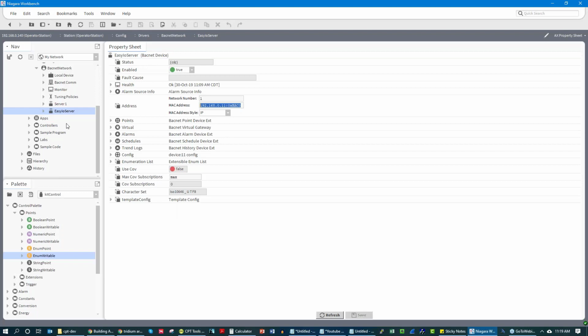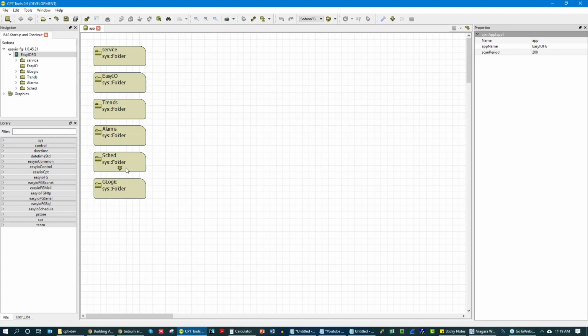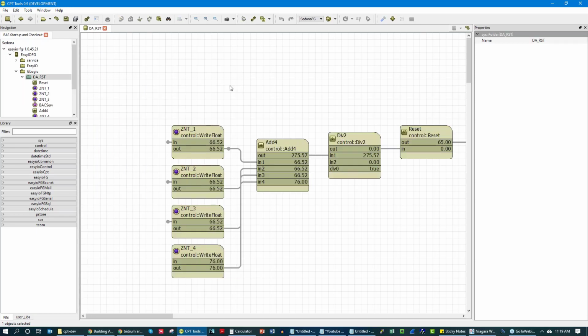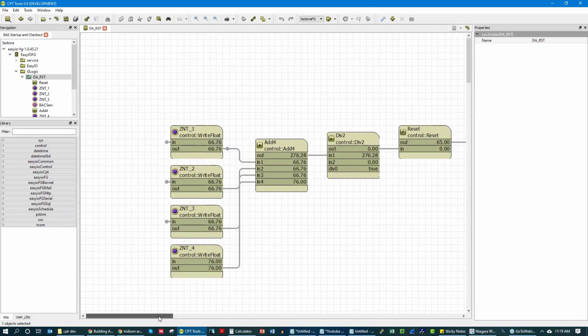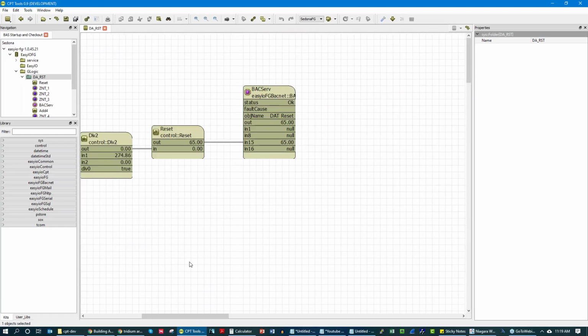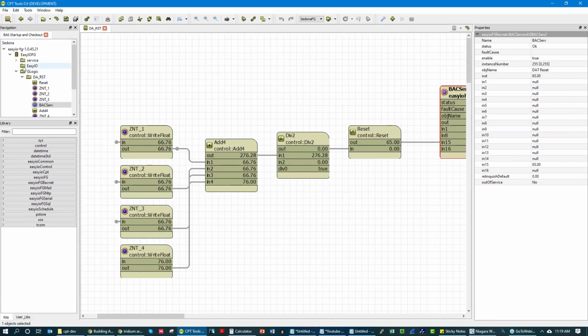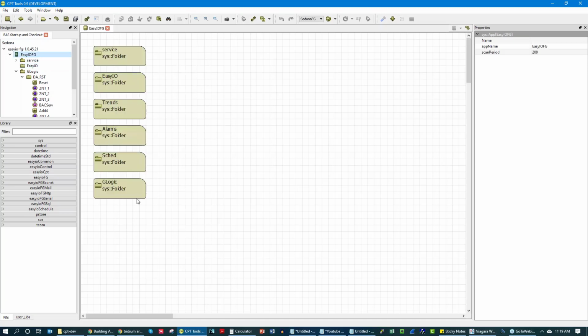So we saw that there we're configuring our supervisory device, we're mapping in our controller, we're discovering our points, but here we've actually got the field controller software itself. And so if we go in here, we can see that we have some logic in here, right? We can see that we have logical points. Let me go over here, show you. We can see that these logical points are coming in and we are actually sharing them as BACnet objects. So this is all logic in here. And we can just look through here and see what we have built into this.